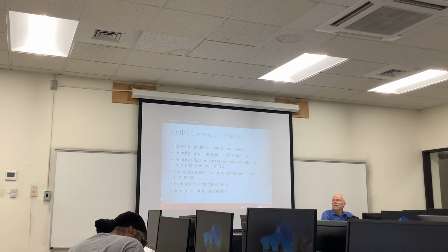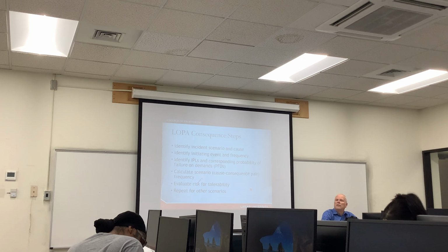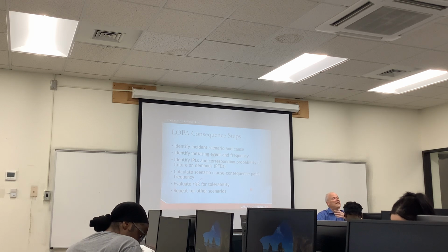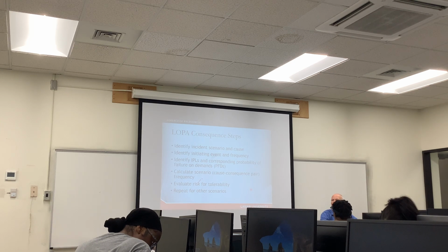There was a case at the AIChE meeting, and the consultant was talking about a case where somebody was suing the company because they had a shutdown system for a rail car filling station. They had a solenoid valve there, and they were supposed to be testing it at a certain frequency. But it's a lot of trouble to actually shut the solenoid valve, or to open it up and see if it actually shut. So they were relying on the little green light that would come on saying that it was being shut.